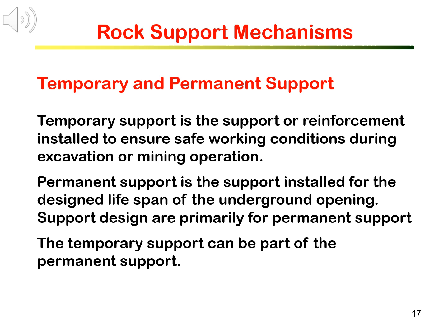Support design we usually do is primarily for permanent support, and it requires considering the stability and the functionality of the underground facility over a long period. The temporary support is usually part of the excavation activities, as it is mainly to ensure the excavation work can be safely done. However, much of the temporary support can be integrated into the permanent support. For example, bolts installed for temporary support can function as permanent support with proper measures for long-term use.